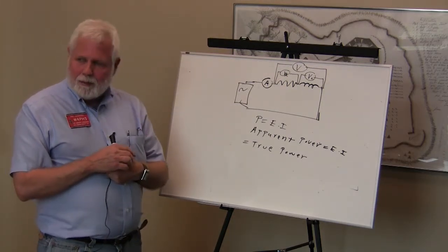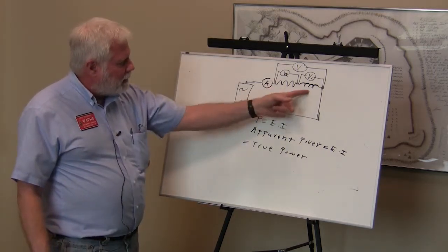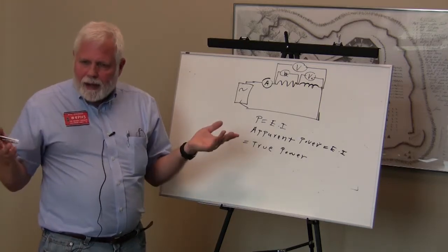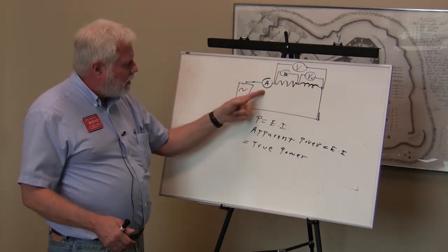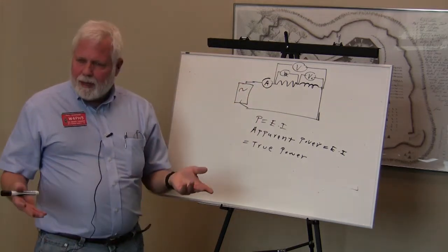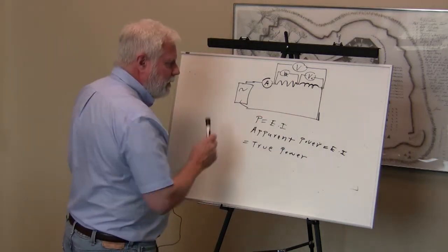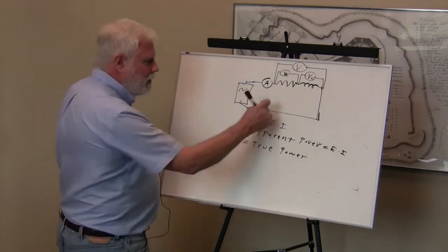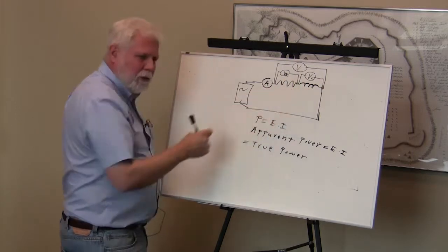It appeared to be using maybe 100 watts. We multiply this out, but the actual amount of heat coming out was maybe only 80 watts. Well, why is it that if we measured the voltage and amps and the apparent power is 100, how in the world can only 80 come out of it? And the answer is that the inductor over here is not dissipating any, it's simply storing it and returning it. The resistor is putting out real power. The inductor is storing it and returning it.